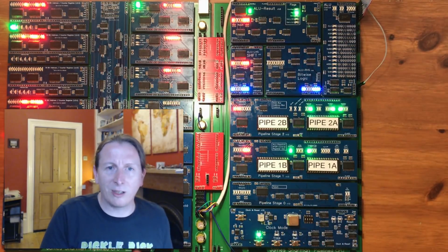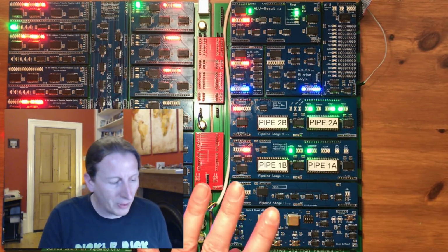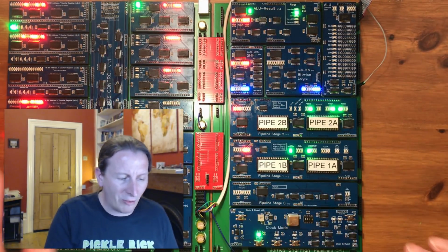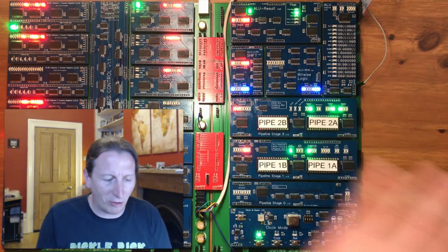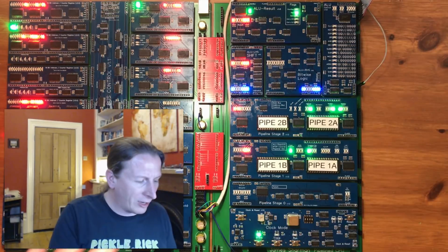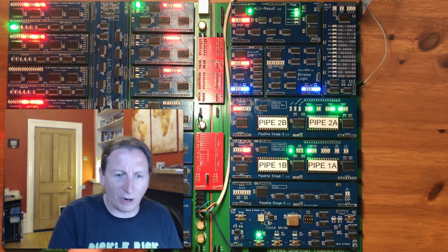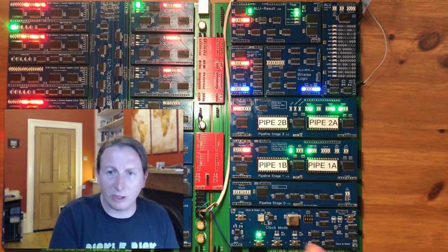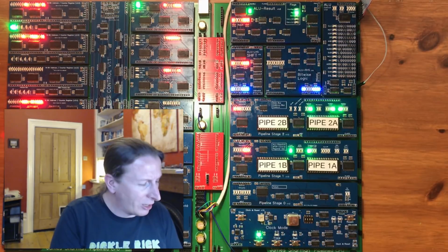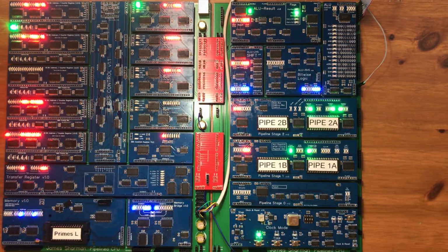There is something more like that in some of the microcontrollers that are out there, and that's one of the differentiating factors between general purpose processors and microcontrollers: they can take those kinds of liberties and not do the general purpose thing. But there are times in programming where directly accessing the stack via other instructions might be useful. So I didn't want to do that. I kept the simplicity, but yes, I've got a hardware stack.